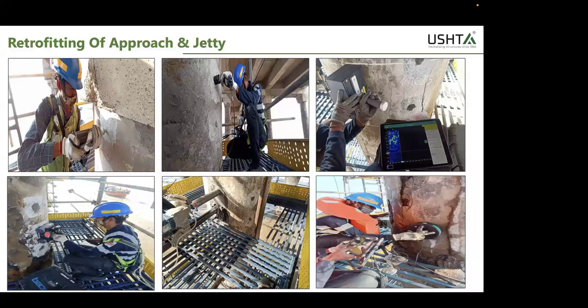As per the codal provision, you should have at least 75 mm of cover in this. Whereas in some structures, when we audit, we only see sometimes 5 mm, 10 mm. So this is also one of the reasons why concrete structures prematurely fail in corrosion.